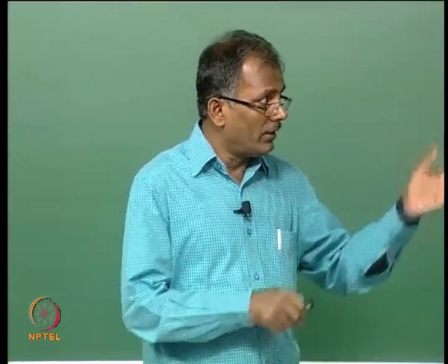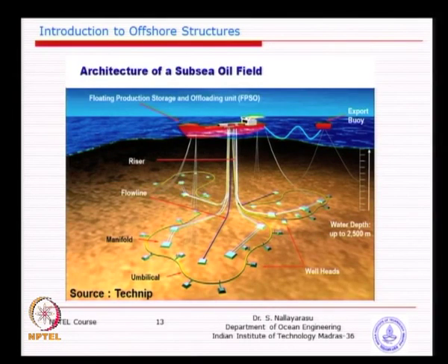The reason why we did not go for this for the East Coast is because it is a cyclone prone area. The FPSO's station keeping could prove to be potentially difficult. Of course, you can design it, but at a larger cost. Instead, if you connect all these lines to a shallow water location by pipelines and make a fixed structure, it could potentially be cheaper.